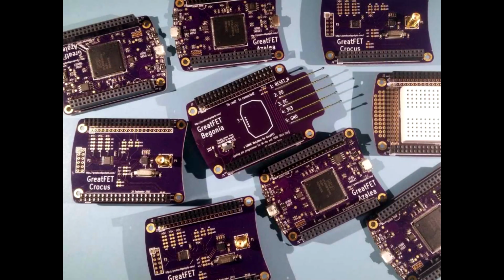So the first thing I want to look at is the GreatFET Project, which is new. Some of you have seen me carrying this around. This is the main board, code name Azalea. If you're familiar with Travis Goodspeed's GreatFET project, this is sort of a next generation GreatFET, and it gives you a high performing, high speed USB peripheral. It gives you a device, like your own custom high-speed USB device that you can control from a simple Python interface on your host computer. That's one of the main goals of the GreatFET project.